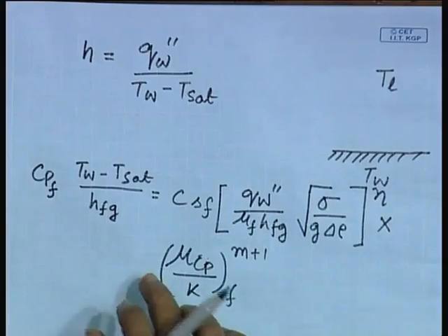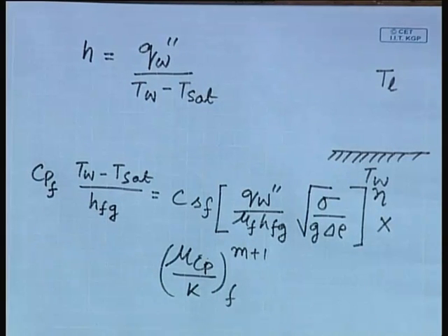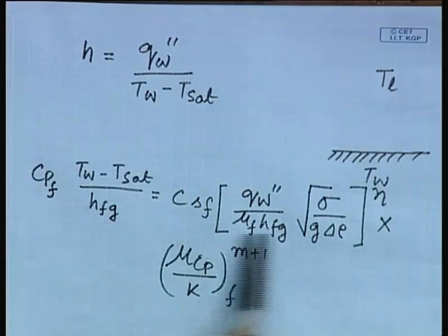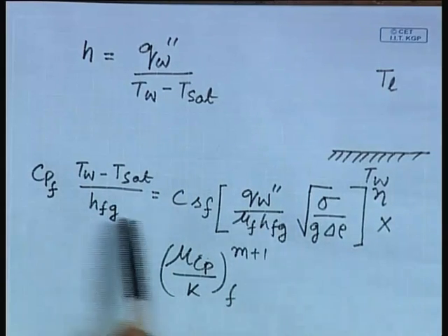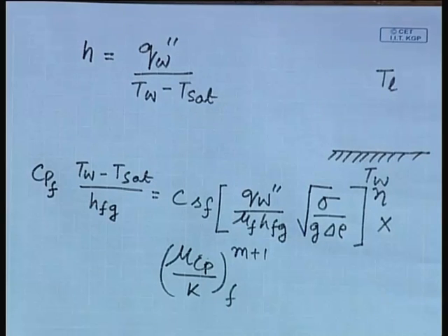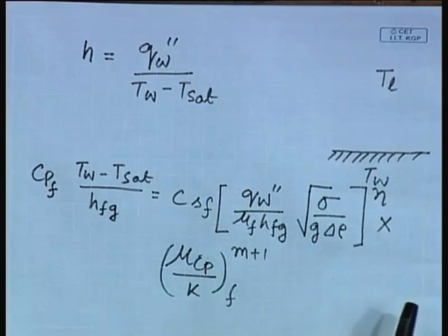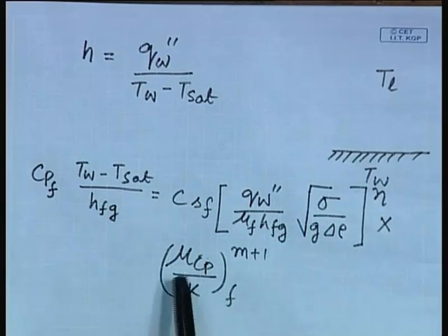So, this is how we will get the relationship for boiling heat transfer. If you see the relationship, you can see that here we are getting a very straightforward relationship between heat flux and the wall superheat, TW minus Tsat. This relationship is correct and applicable for the range of nucleate boiling. So, part of the boiling curve you can construct with this relationship.